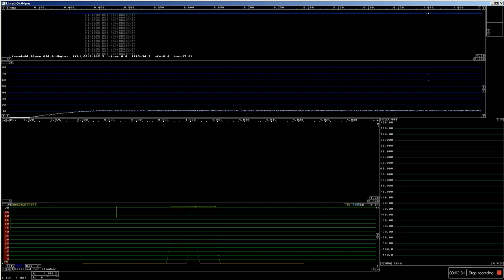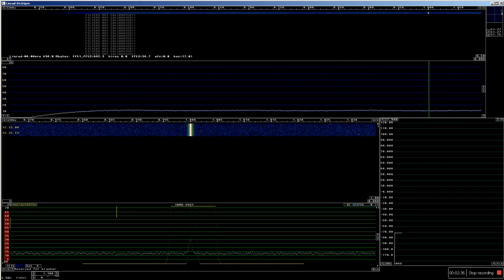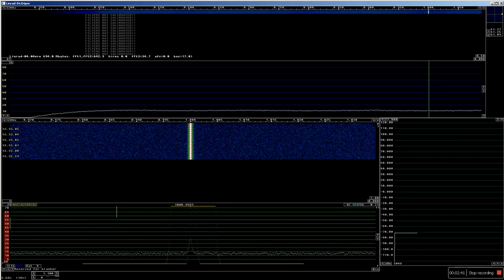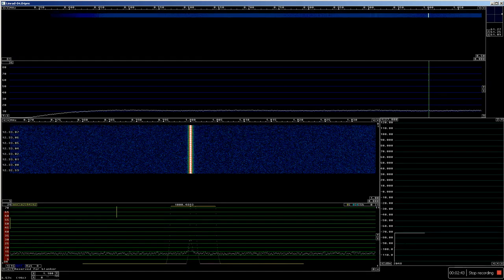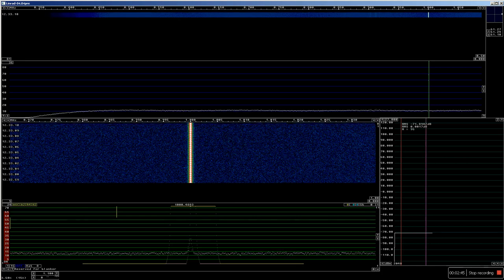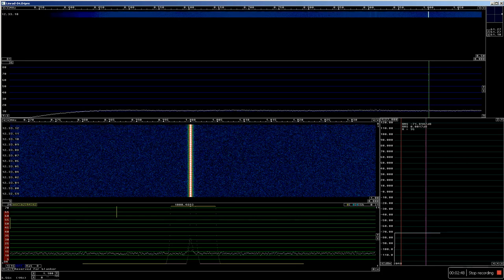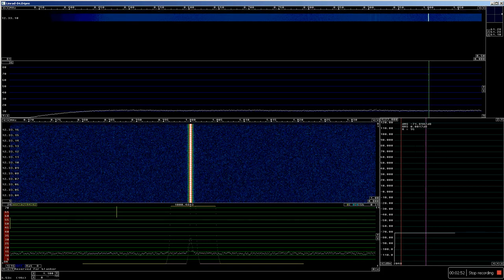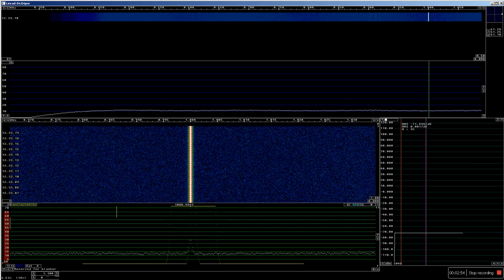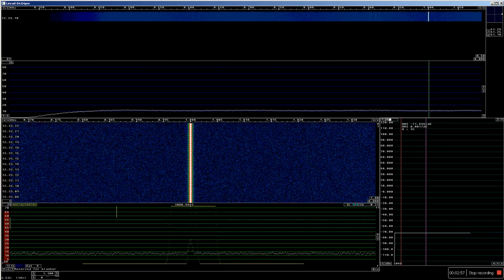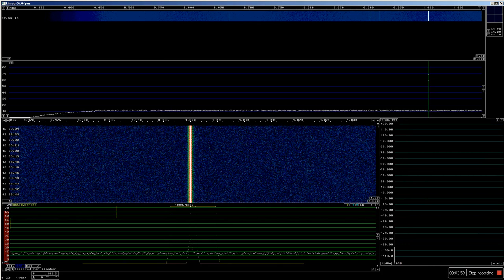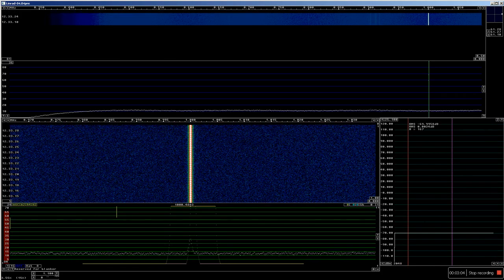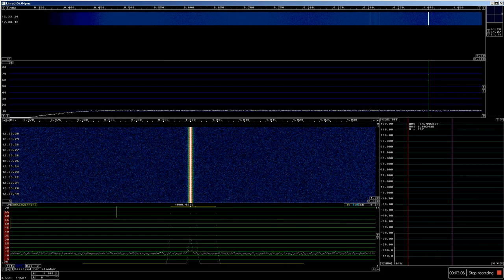So I click on the signal again. It moved since I changed the FFT bandwidth. And we can see it didn't change much, just a little. I can read here. It says minus 71.9. So it should be, I think, 25.1 here. Now it shows minus 70, just like the signal generator.